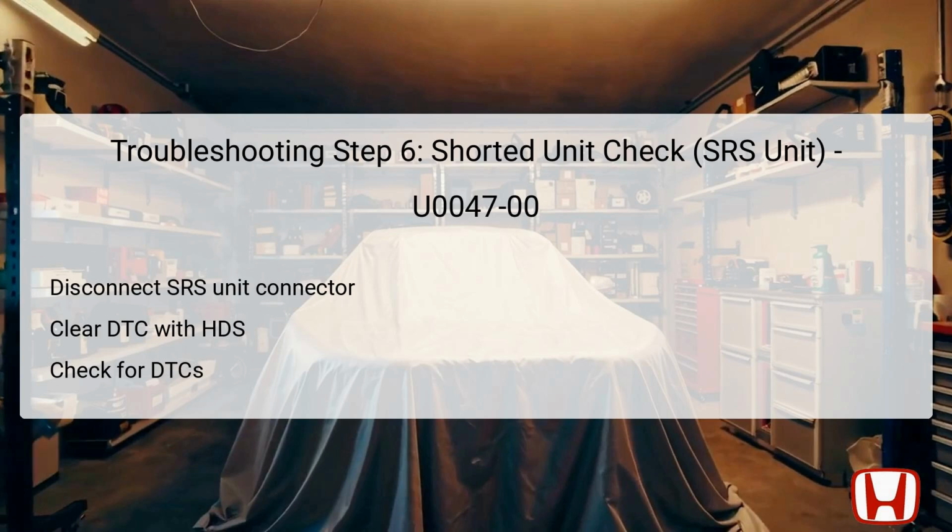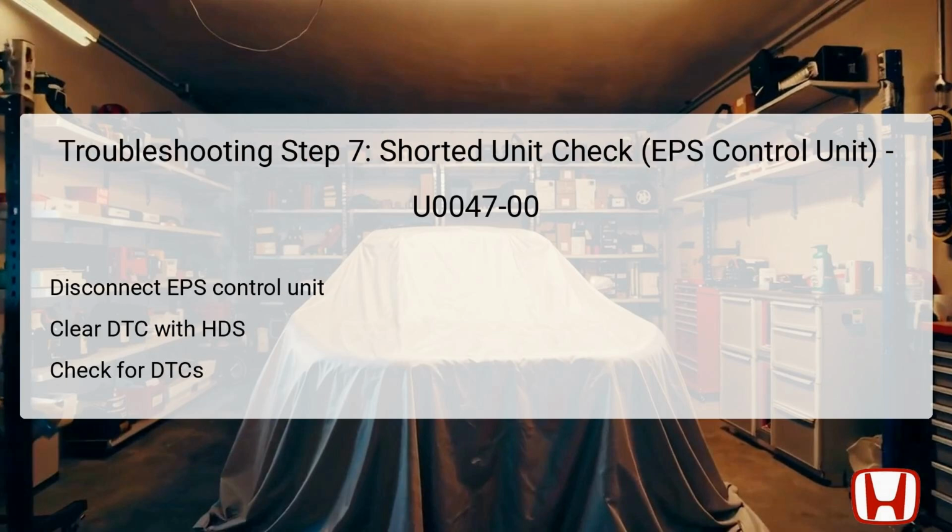Once disconnected, switch the ignition to on to reset and clear the DTC via the HDS. Repeat the power down and wait for 6 seconds before restarting. Finally, determine whether DTC U0047-00 remains active. If it does, there may be other components involved that need to be verified in the interconnected system. The next step features the inspection of the electric power steering EPS control unit to check for potential shorts